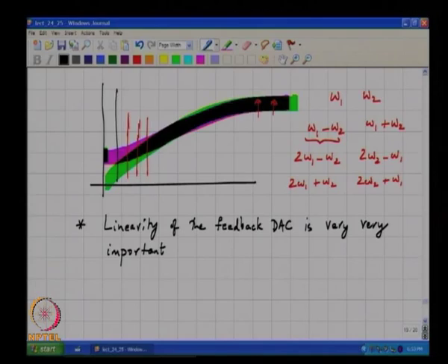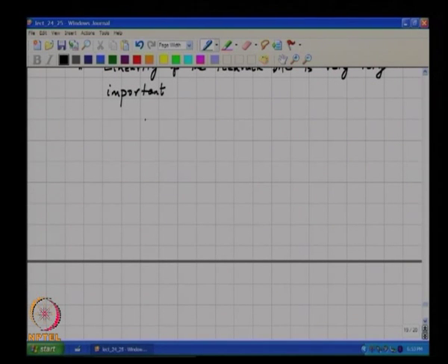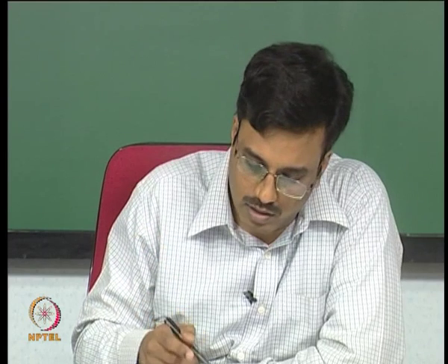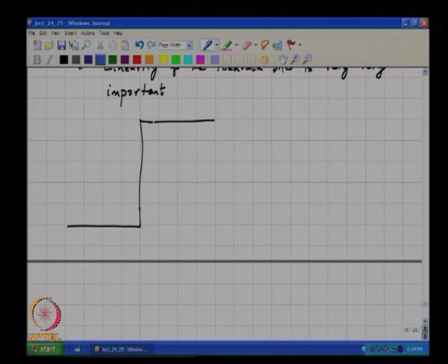So, this is regarding a multi-bit modulator. Now if we change the scene and do a similar analysis for a single bit modulator, what do you think will happen? An ideal single bit quantizer's transfer curve must look say like this. What do you think will happen if you have a non-ideal single bit quantizer? I mean you have a single bit A to D and a single bit D to A, right. So, the ADC threshold not being correct means that the staircase will shift horizontally,